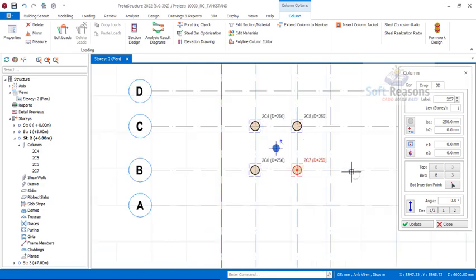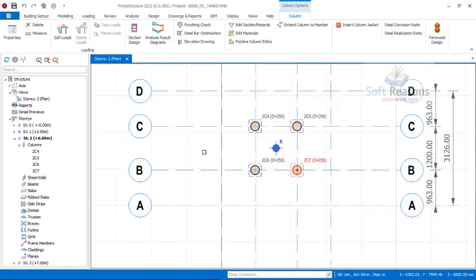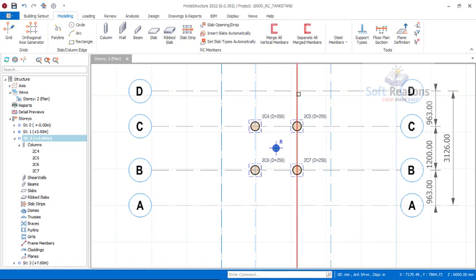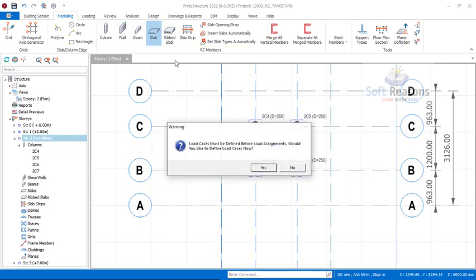Okay, just like this. All right, so this is the top of level 2. You can see it from here. So we can now create our reinforced concrete slab. Mind you, we are designing this using a flat slab, and from what we have there, we are considering a slab of thickness 185 millimeters. All right, we are considering a slab thickness of 185 millimeters.